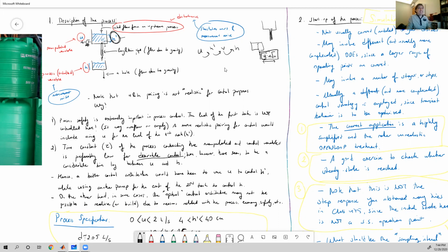Why do I emphasize this thin pipe? Because in a thin pipe there is going to be high friction due to the small radius. Now, at a certain height value, the velocity here will not be directly equal to this value. Here, velocity will be determined by the pressure difference between the two ends.